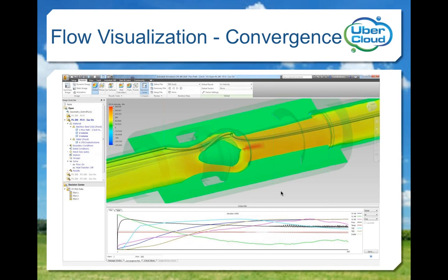The results window displays a chart of several key parameters as the program iterates a solution. Since I've asked the program to calculate the volume flow rate, the V sub X trace is of interest, and after 500 iterations, did not look like it was going to settle down. And other parameters did not look like they were close to flattening out either. Again, the multitude of settings in the software was still set to default values, and I thought, let's just run another 500 simulations.